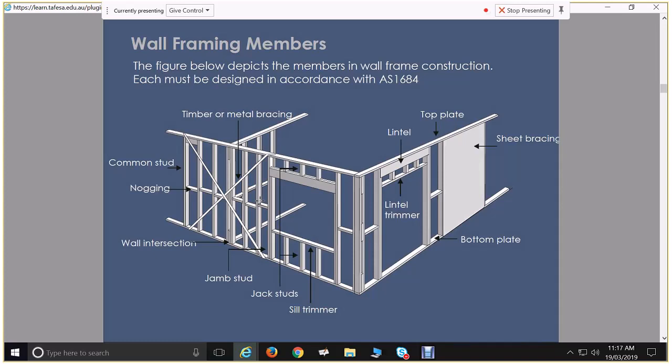So some of those situations you can work through the timber frame code and make all these decisions, but sometimes when it comes to studs, what we used to do in the office is just have a note on our timber frame that says double studs to all openings. And then that's problem solved. Double studs to all openings also enables really nice seating of that lintel.